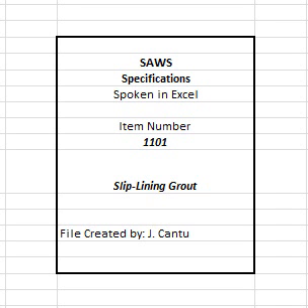The contractor shall test the integrity of the installed liner pipe and constructed bulkheads for any leaks by performing the following. A. Dewater and inject dye water into the annular space.